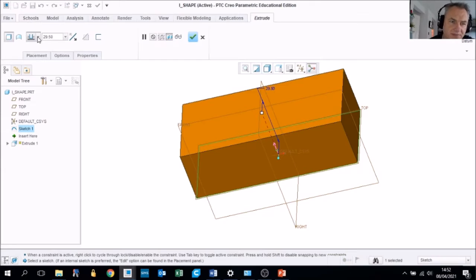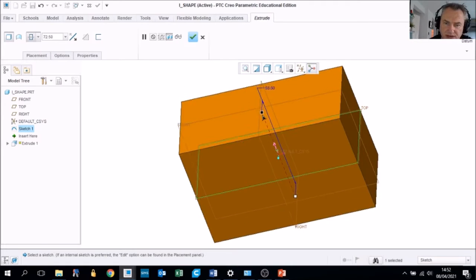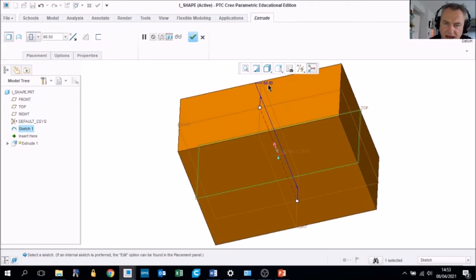Now this time, I showed you this in the last tutorial, I'm going to extrude both ways, okay, so on both sides of my extrusion. So I want you to start using that tool, that's very helpful. And the total height is 120 millimeters for this object.